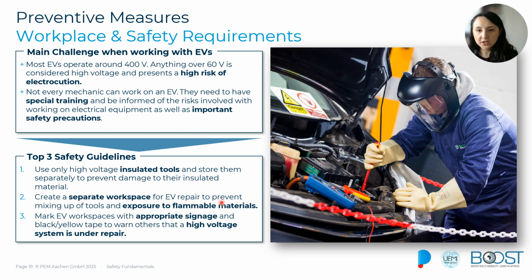The second safety measure that we can have in general is to have dedicated workspaces for high voltage and for electric vehicle repairs. Mixing high voltage work with general mechanical repairs will only increase the risk of contamination, of not using the right tools, and of exposing, for instance, people to flammable materials and so on.